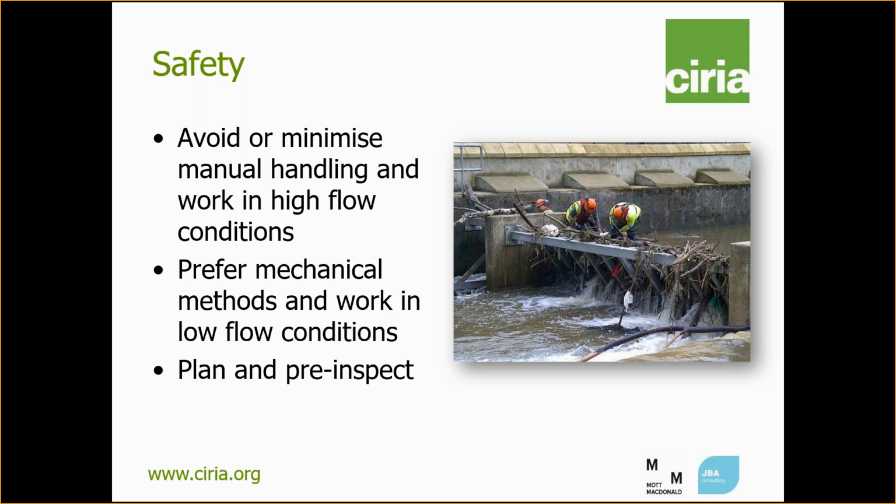But we acknowledge that culverts, screens and outfalls can't be avoided in all instances, so if they have to be constructed or retained, then we should try and avoid or minimise manual handling and use mechanical methods instead. We should aim to work during low flow conditions rather than high flow conditions if possible. And if work during high flow conditions is unavoidable, we should provide safe access for vehicles and pedestrians. So we want to see a move away from the situation that we can see in the photograph, where we've got operatives standing on a screen with probably quite deep water nearby.